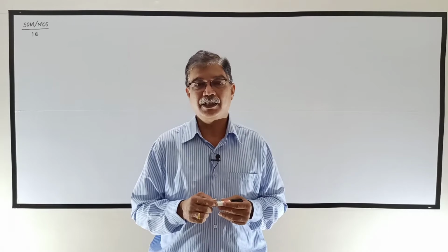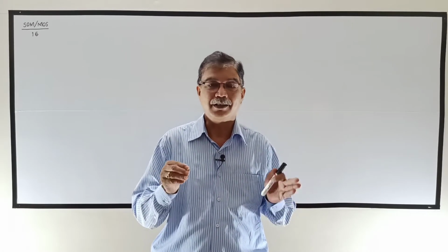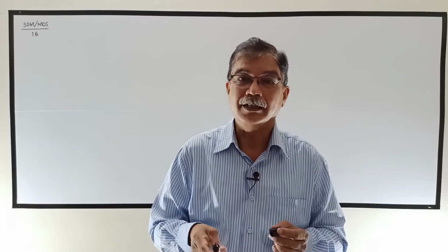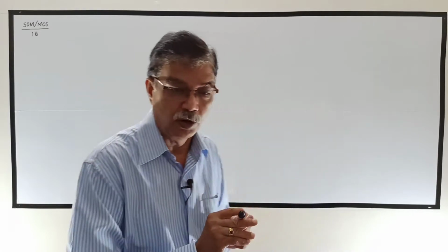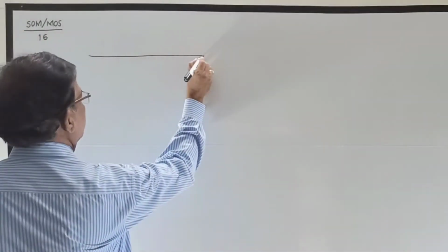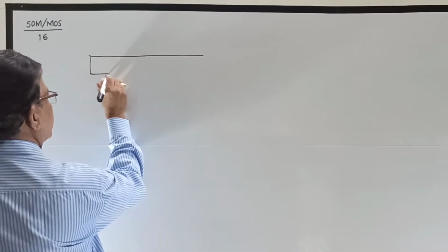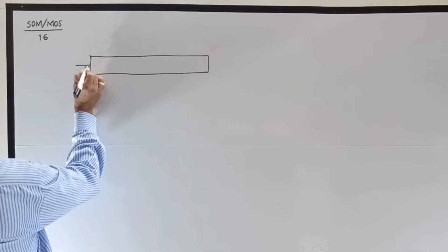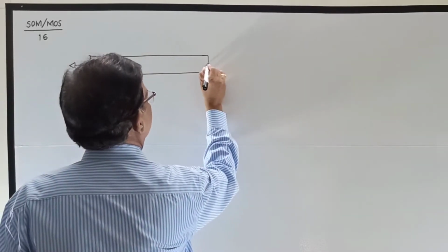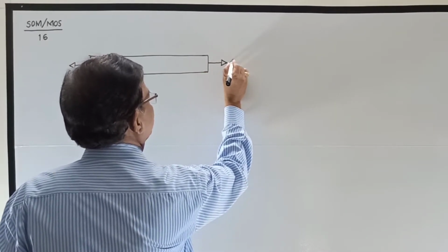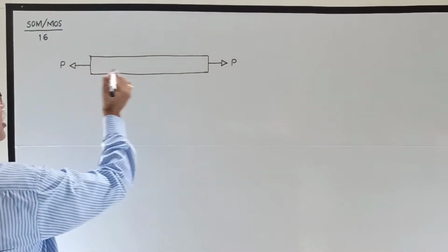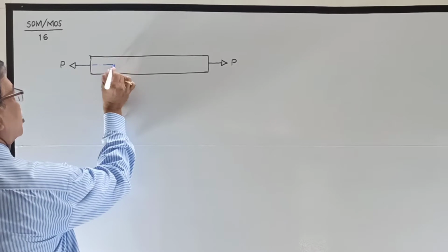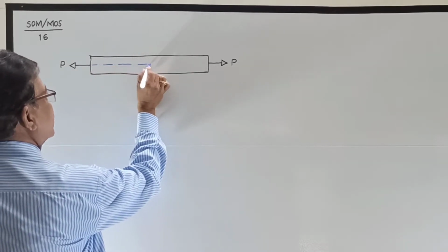We know that whenever we consider a body of elastic material, when external loads are applied, it will deform. Now this deformation of the body is resisted by the material of the body. For that purpose, let us consider a bar of elastic material. Let us say that it is subjected to axial tensile load, say P. In the last video we saw what is tension. Because they are of pulling nature, it is tension. Axial tension. Why it is axial, that also you know. Because the load is acting along the axis of the body.